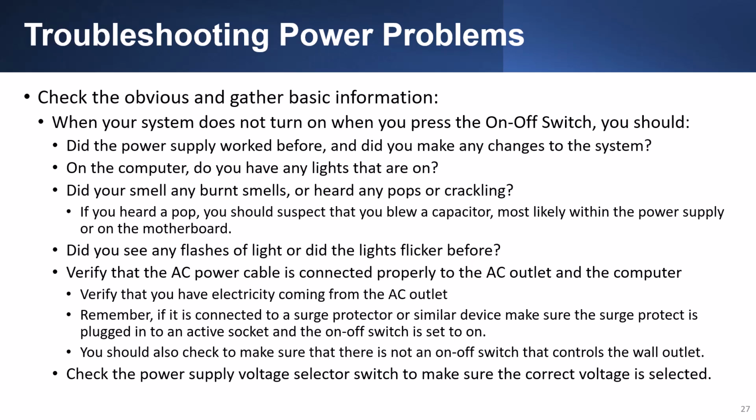Verify that the AC power cable is connected properly to the AC outlet in the computer. Verify that you have electricity coming from the AC outlet. Remember, if it's connected to a surge protector or similar device, make sure the surge protector is plugged into an active socket and the on-off switch is set to on. You should also check to make sure that there is not an on-off switch that controls the wall outlet. Check the power supply voltage selector switch to make sure the correct voltage is selected.